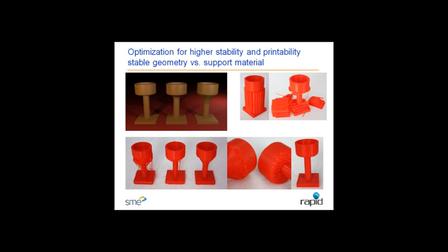The easier approach is to use support material, which is a must if the design is totally fixed. But it has some drawbacks, which I don't want to mention during this presentation. Or we can optimize the geometry by defining a bridge or fillet to make the design printable, so we don't really need a support material. Of course, the 3D printing expert should have the knowledge of both and probably use both techniques depending on the design and requirements.